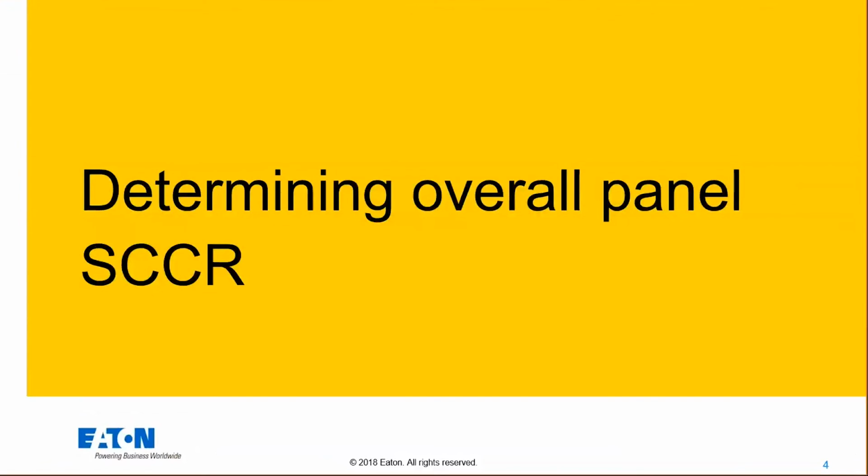And then we have a question in the chat box. Somebody asked, when do you have to take into consideration the high fault rating? Is it specifically used to raise the SCCR rating of a panel? You take into consideration the high fault rating if you want to, quite frankly. If you want to get a higher SCCR rating in your panel, then you would have to use that high fault rating. In my example yesterday, I had a contactor with a standard rating of 5,000 amps. If I want to get that over 5,000 amps, I would have had to use another device in there. I had to use a Class J fuse, I believe, a 20 amp Class J, and that would get a higher rating.